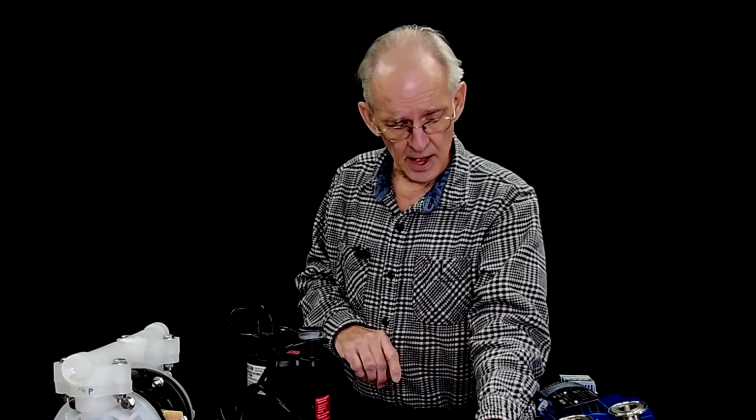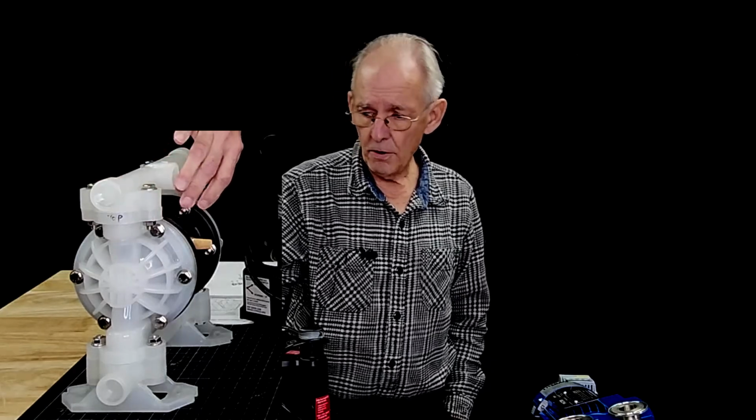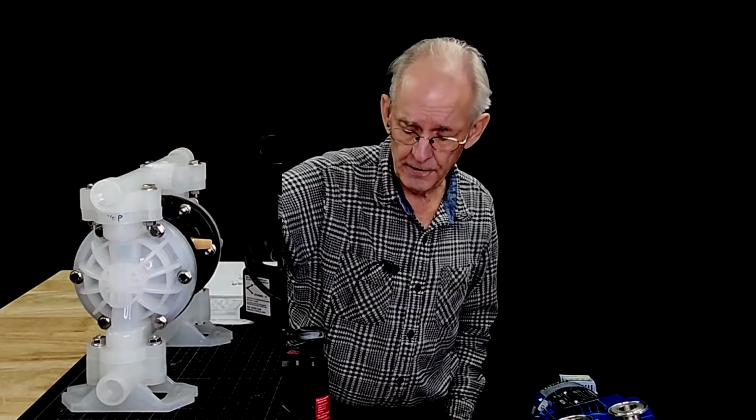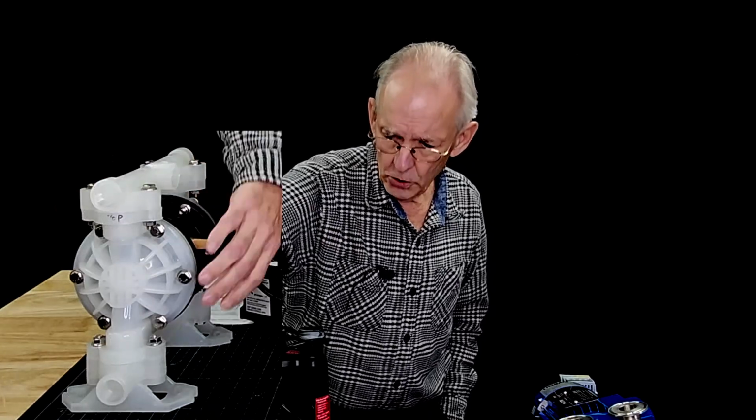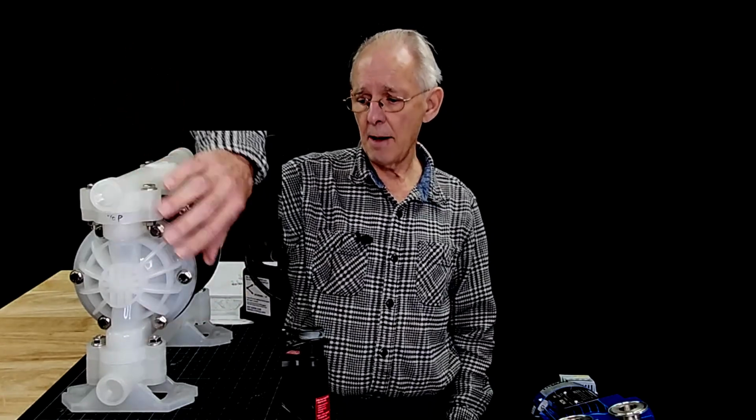Okay? So then we have one more positive displacement. This one is an air pump. This is double diaphragm. There's a valve section, and the air goes back and forth and pushes it. And there's 4 ball checks because this is double diaphragm. And the flow comes in the bottom and goes out the top through these ball checks. Same thing, it's positive displacement, but it's not reversible. It can only go in one direction.